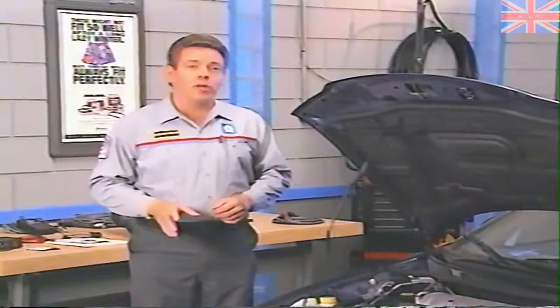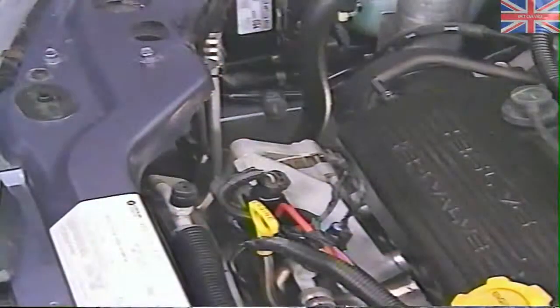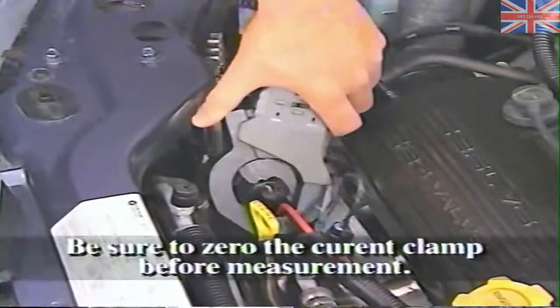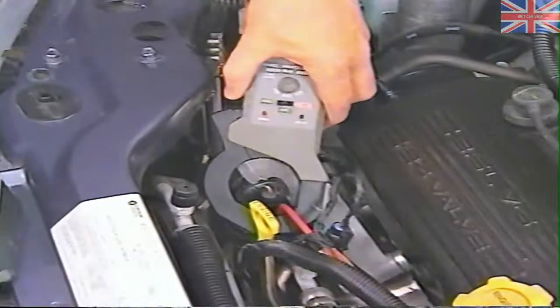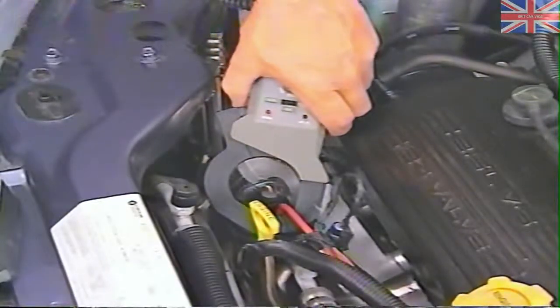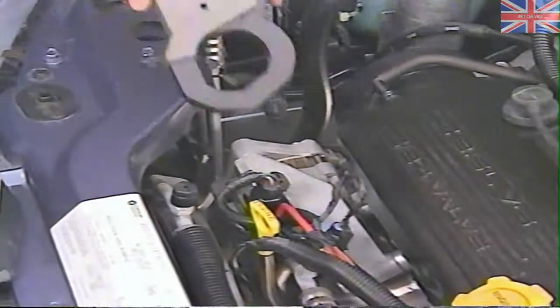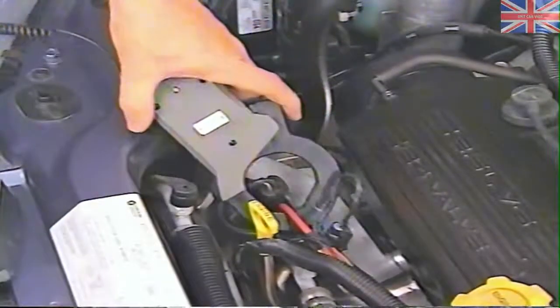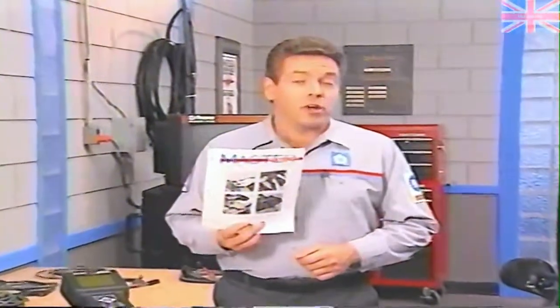High range current readings up to 2,000 amps are done using the current clamp. Place the clamp over the wire to be tested and select the appropriate range, 0 to 200 or 0 to 2,000 amps. Remember, the clamp should not be used to test current under 10 amps. If you should happen to get a negative current reading on the DRB3, simply turn the clamp around. See the January 1994 MasterTech for further discussion of both the clamp and the shunt.